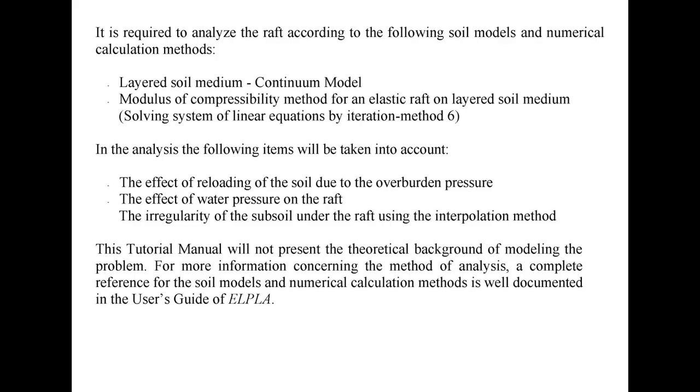It's required to analyze the raft according to the following soil models and numerical calculation method: layered soil medium, continuum model, modulus of compressibility method for an elastic raft on layered soil medium, solving system of linear equations by iteration method.